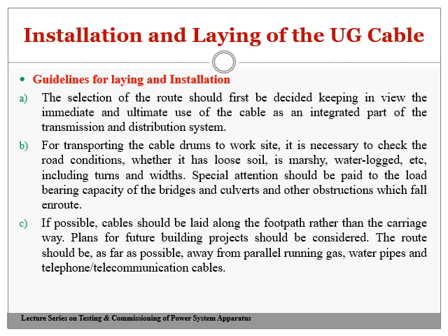Now, I want to transport the cable from the manufacturing area to the installation area. It is always necessary to check the road conditions, whether there is loose soil, marshy or waterlogged ground, or turns on it.